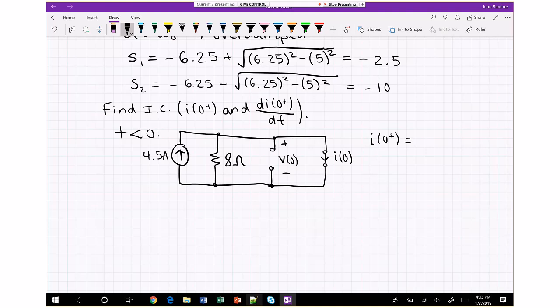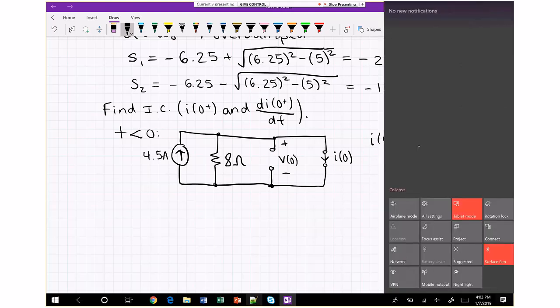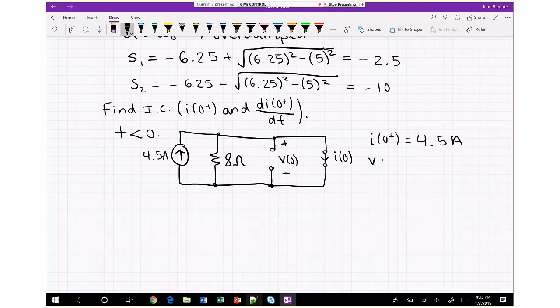No voltage across the resistor means no current through it according to Ohm's law. So that's why by inspection, all the current will flow through that short. Again, because it's a short, there's no voltage on it.